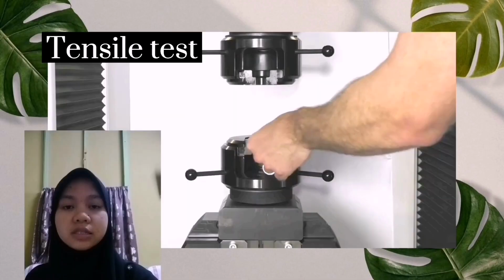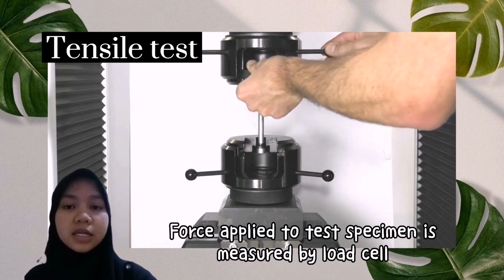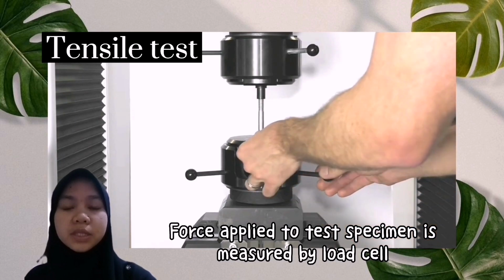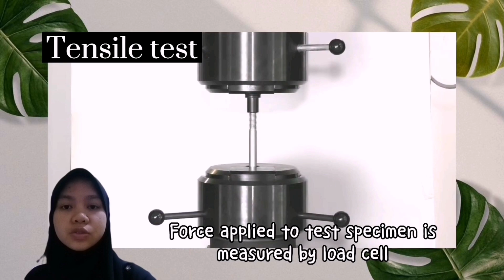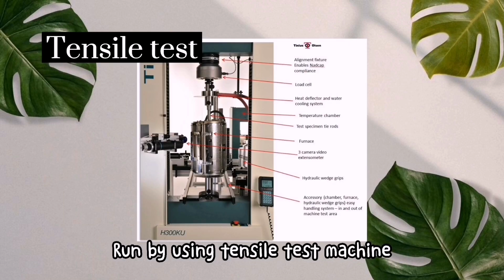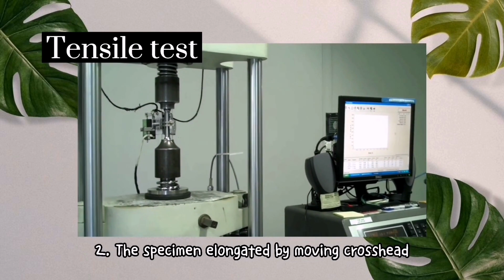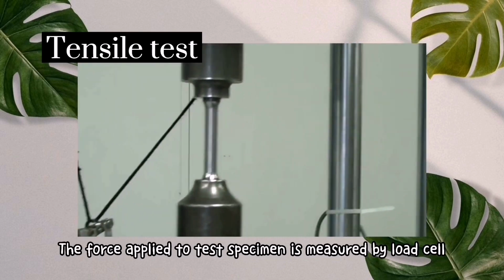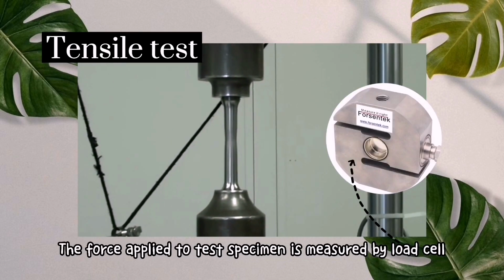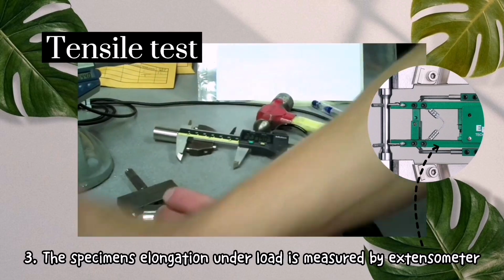And the next one is the tensile test. This test is one of the most basic and common types of mechanical testing. It applies a tensile pulling force to a material and measures the specimen's response to the stress. By doing this, tensile tests determine how strong a material is and how much it can elongate. The test is run by using a tensile test machine or universal testing machine. Firstly, the ends of the test piece are fixed into grips. Then, the specimen is elongated by the moving crosshead. The force applied to the test specimen is measured by the load cell. And lastly, displacement or elongation under load is measured by an extensometer.